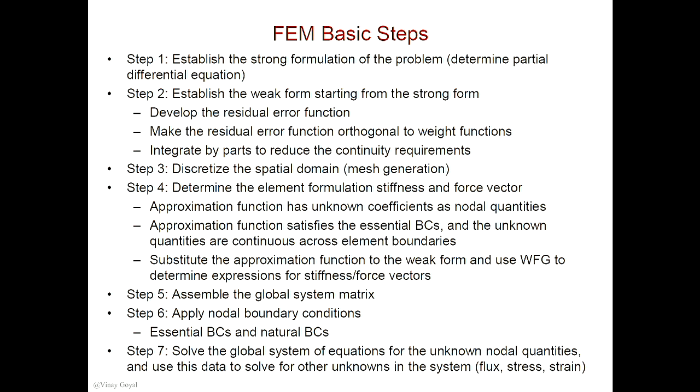By decoupling these two, now every element will have a Jacobian, and now I can just solve the partial differential equation over a standard element. And what I will do next is assemble the system together. Once I assemble the systems together, I apply the loads, I apply the boundary conditions. Now I'm able to determine the stresses, strains, displacements, and so forth. Although we haven't done that yet, we did it for heat transfer where we determine the temperatures. Is that correct? Okay. So if I summarize this slide for you,